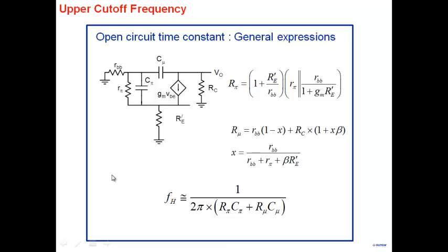All of these simplified methods are based on the dominant pole. One should not forget that the origin of it is one single pole whose frequency is dominant compared to the other poles and zeros in my system. And in common collector, it so happened that the dominant pole was cancelled by a zero. The non-dominant pole then became the key factor, and the upper cutoff frequency was much higher.